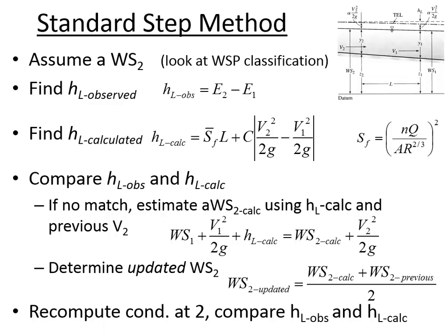So in class on Tuesday, we had different rows on the spreadsheet. And what did each one of those different rows represent? Why did we have multiple rows? What were we breaking up into pieces? The water surface curve, right. So remember, we had lots of rows in our spreadsheet because we had a curve that we didn't want to approximate as a line. We wanted to approximate it as a series of little line segments that together would better approximate the shape of that curve. So that's why we had different rows in our spreadsheet last time.